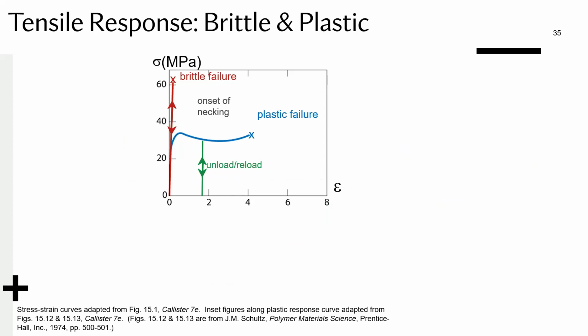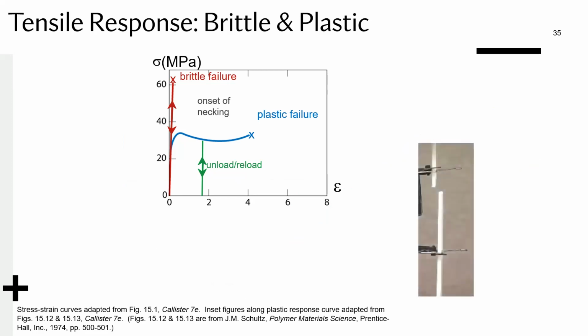So let's first look at how these three different types of polymers behave on a point-to-point basis, like what you already did with metals. So let's first look at brittle failure. This happens in the shape that you see here. Basically, if you do that tensile testing, you'll see that the specimen has a very gritty crack there, and you can actually see a sharp boundary there, and it happens rather fast in terms of elongation. It doesn't increase in length that much.